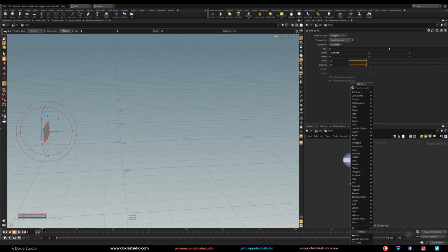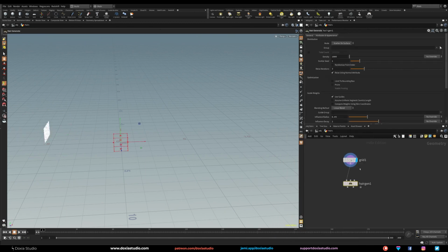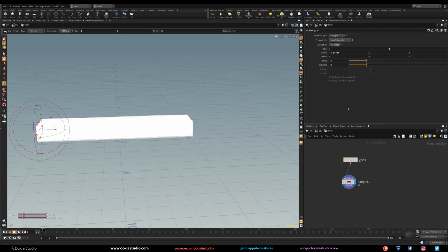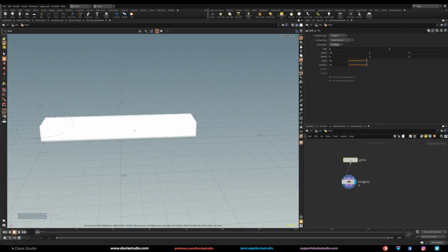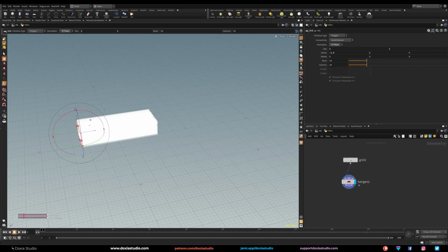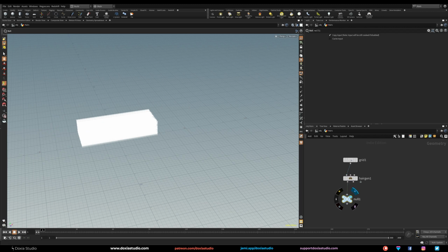Something like that. Let's place a hair gen. Okay. And we don't want guides, right? We want the length to be, let's go with 10. Let's put these on -5. So we know that we have this center. And maybe let's even lower these. Don't need that big. -2.5. Okay, something like that. So this will be our hairs. So let's place a null. Let's go with base splines.